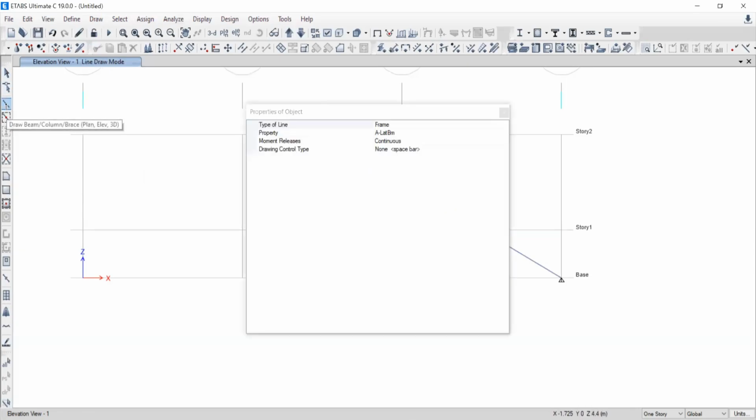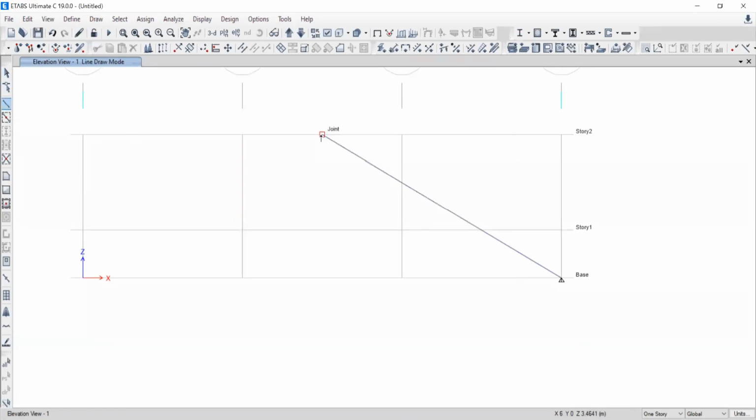But if I take the frame, close it, I'm taking the line from here to here. Now I have to take the line again from this point to this point. I will take the help of this continuity and the active command. Click over that. Now I don't want to draw the line here. I would like to draw the line from here to here only. So I need to stop the continuity. Right click, continuity will be stopped. Now click on this first point, the command is active. Click on this first, move to this. This is done. Clear or not, Pratik?